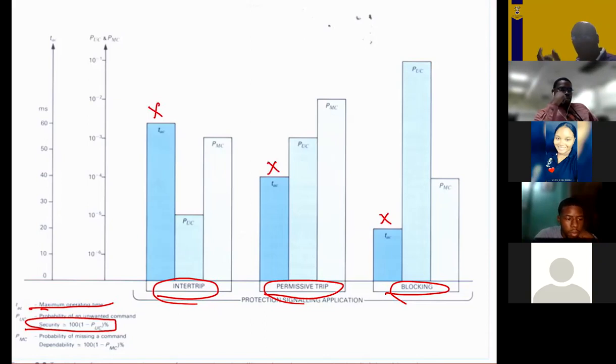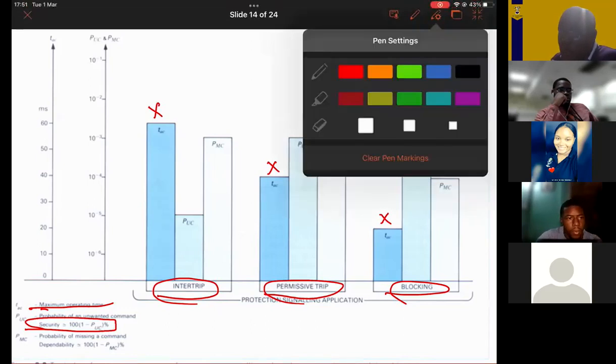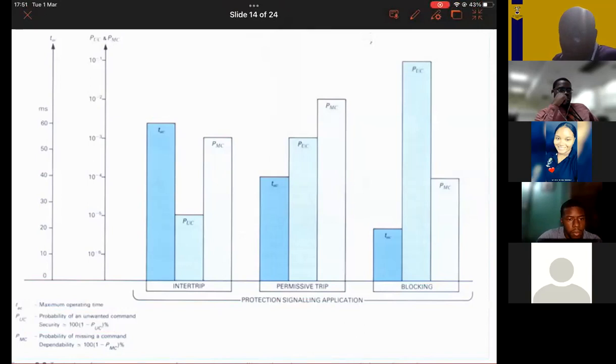And that is the higher level of reasoning that we had last week, Mr. Johnson. But the others, I'm sure, remember that level of reasoning. Right? So, because nothing appears instantaneously, the blocking scheme would be the fastest. All right. So in terms of operation, your blocking scheme would operate fastest.